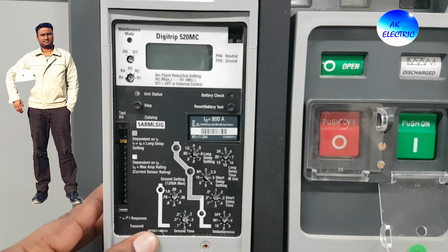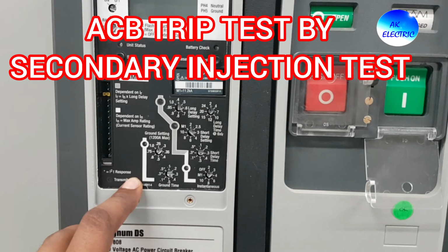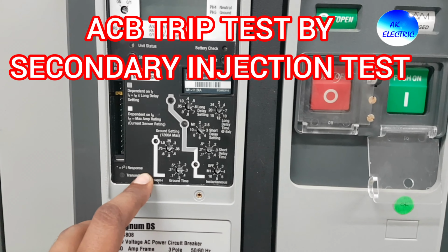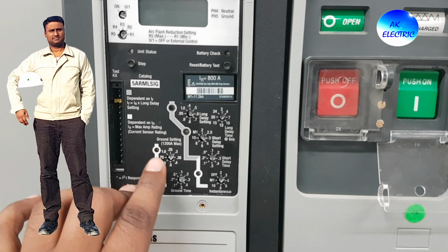This is an ACB breaker. For this ACB breaker, we have to check the trip test. The trip test can be done by both primary injection as well as secondary injection. Now we will see the secondary injection trip test.